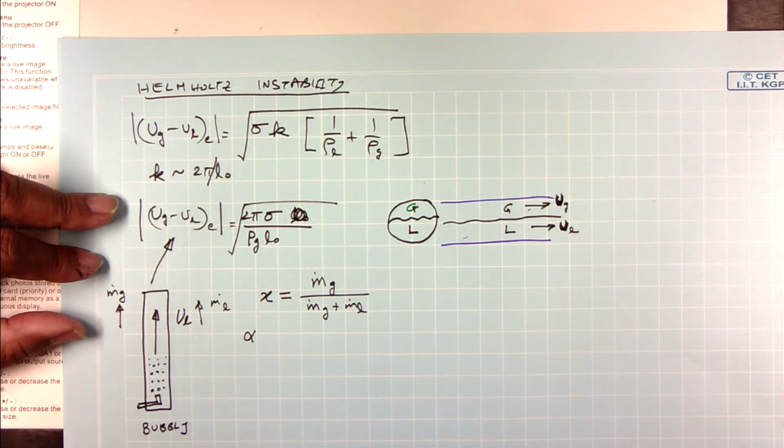Okay, the quality is very easy to determine. You have a two-phase flow in a pipe, you just bleed it into a container, measure the amount of liquid that you collected, and the rest has escaped as vapor. So therefore you know what the quality is. You can collect the liquid over a certain amount of time, or you can condense the other one.